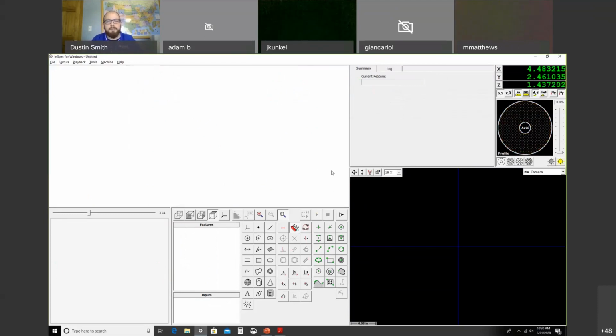If you have 2D parts or you know your machine and your parts pretty well, you can set lighting values and your zoom, but I find it easier, when you actually implement the program on the machine, to set your lights, because you can really see what it is. But once you get pretty advanced with programming on the offline seat, you'll be able to set your light values and stuff before you even implement it on there.